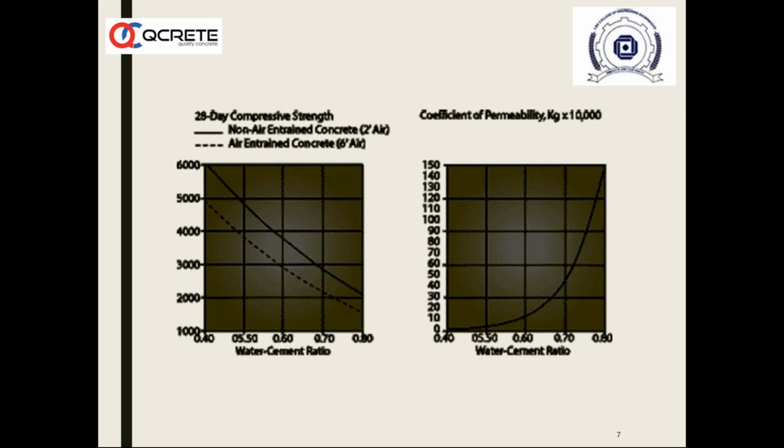If he goes on adding water, he is shifting the water cement ratio to the right hand side and hence deteriorating the concrete from M40 to M24. So our most important responsibility as a QC engineer or an engineer on site is to never allow addition of water. If you do, you are indirectly hampering the strength of concrete.